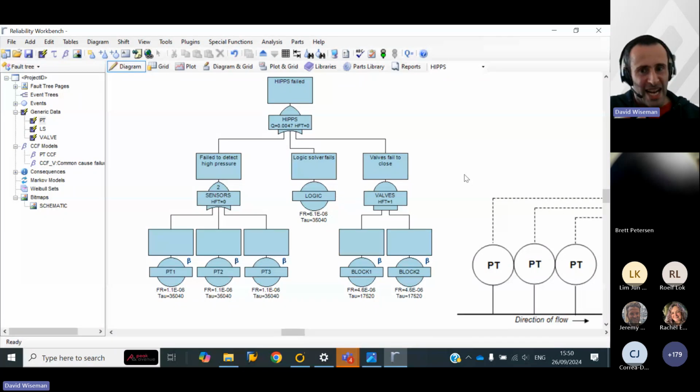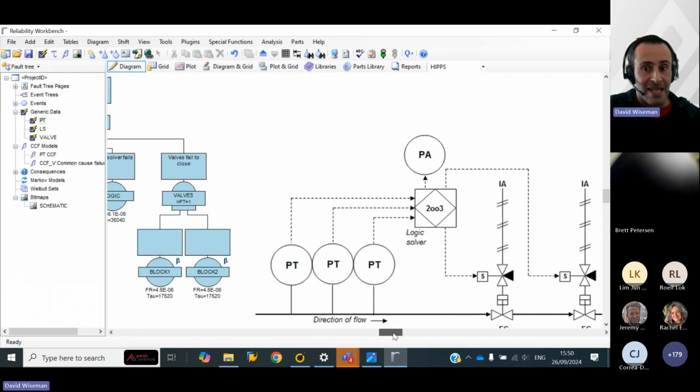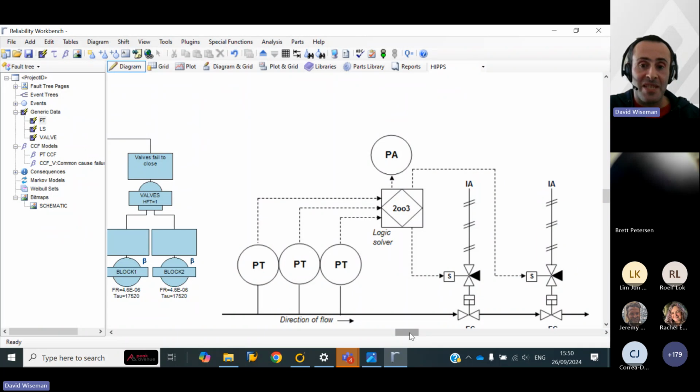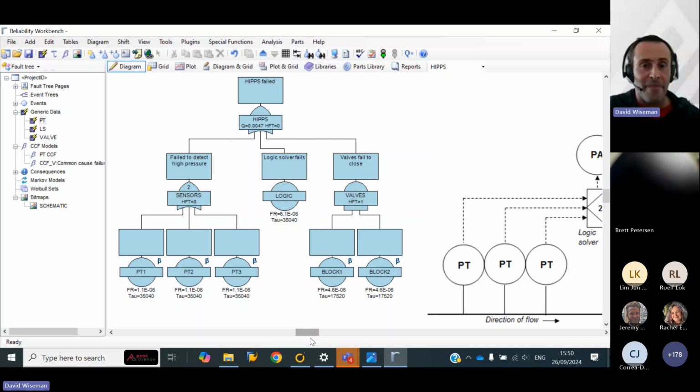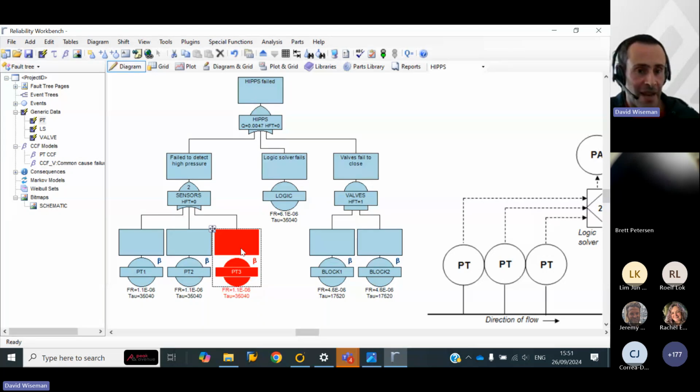That's it, really. We have, starting with our schematic and our understanding of the way this safety system is supposed to work, we've built a fault tree diagram using that top-down method of saying, well, if this is the event we want to learn about, this dangerous failure of our safety system, what would be the direct causes of that problem? We identify those causes. Where possible, identify the causes of those problems. And once we've got to the bottom of the fault tree, we terminate with basic events, the most fundamental events about which we plausibly could have information.